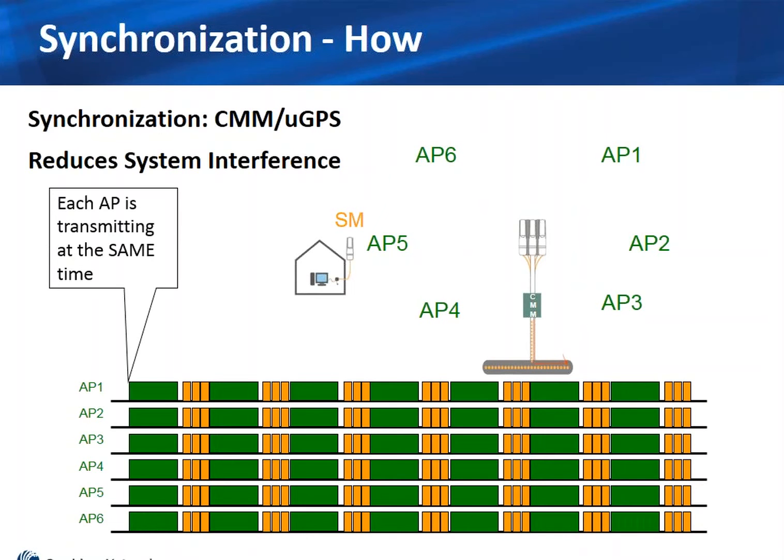So now when they start their duty cycle, that TDD cycle of transmitting in one direction and then transmitting in the opposite direction, they can all be perfectly synchronized so that none of those access points are transmitting when a neighboring access point is receiving, thereby blasting into that access point's receiver and desensitizing it, causing interference and spiraling into losing the efficiency of that whole sector.